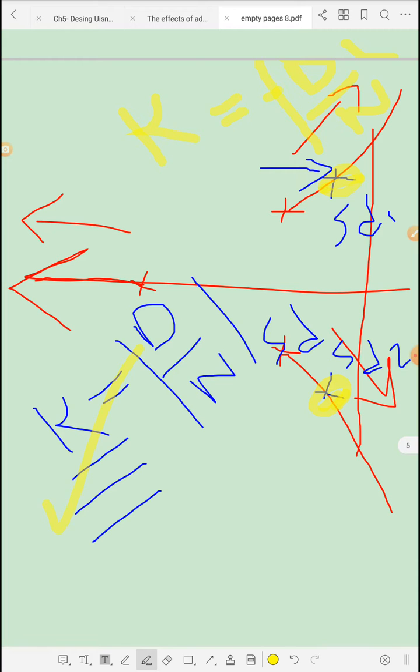This means there is no need to add poles and zeros, there is no reshaping process, and we only apply the magnitude condition K at the desired location for the old system, and our design process is over. This is what I mean by gain adjustment.